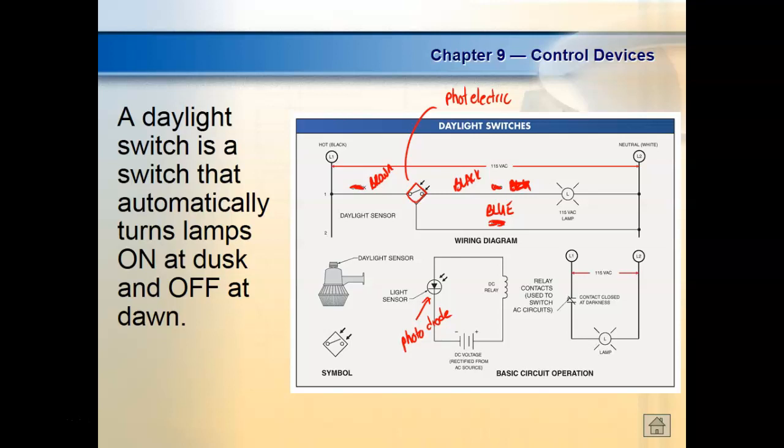This sensor is passing around. That's an AC sensor. Runs off 120 volts AC. So what that means is you could literally swap the brown and blue. Can't swap the black, but you can swap the brown and blue and it would still work. But this is the industry standard way. You need to do things according to industry standards, right? You understand? And we'll talk about that too when we get into some of our circuits that we connect.